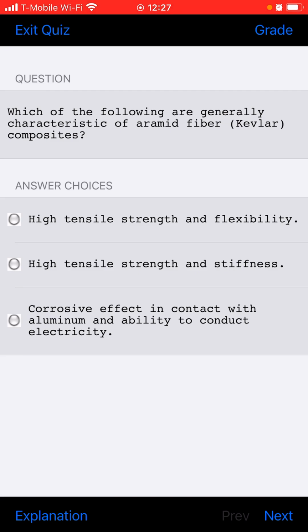Rivets are heat treated before they are driven to soften them so they will not split when they are driven. If a streamlined cover plate is to be hand formed using a form block, a piece of dead soft aluminum should first be placed over the hollow portion of the mold and securely fastened in place. The bumping operation should be...